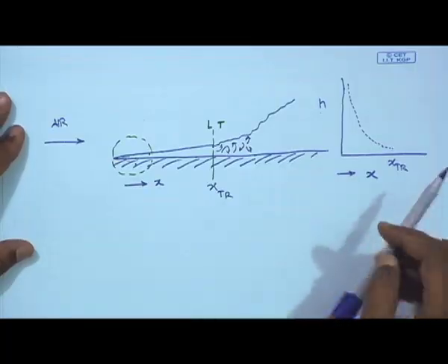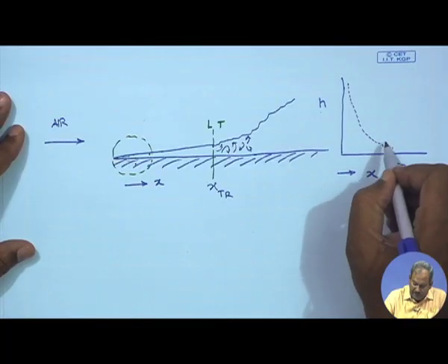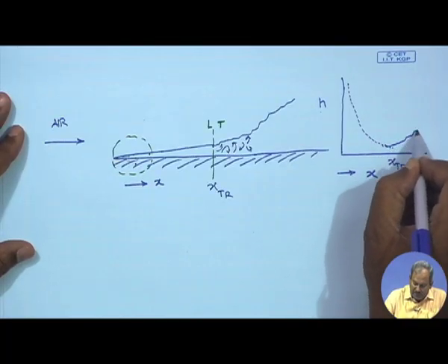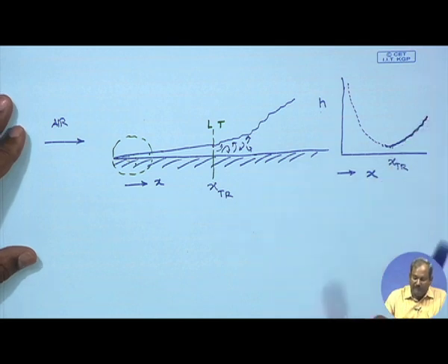So there is not only heat transfer by conduction, there is vigorous heat transfer by convection as well, and the boundary layer will grow accordingly. Same with the hydrodynamic boundary layer or species boundary layer. So in this figure, at the transition, the value of the heat transfer coefficient will increase again.